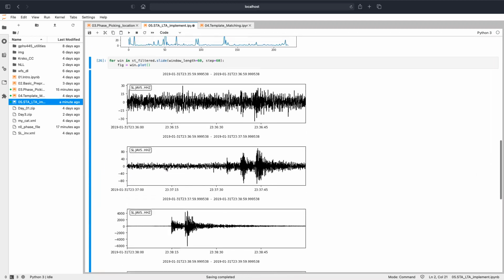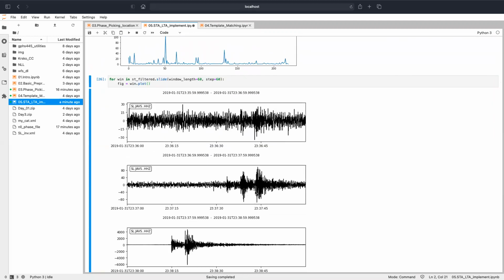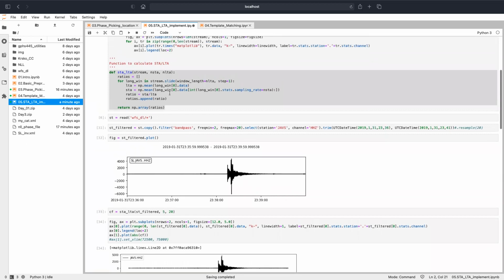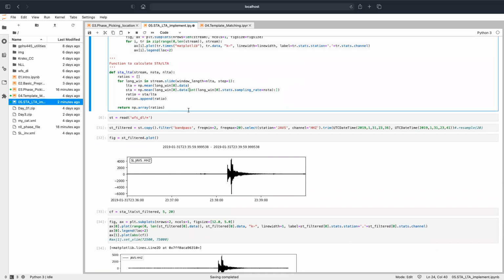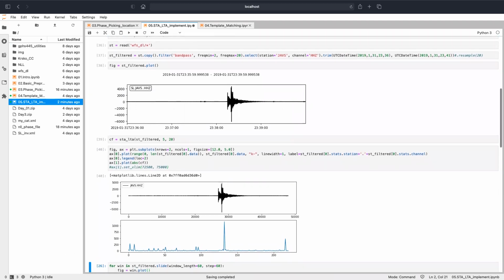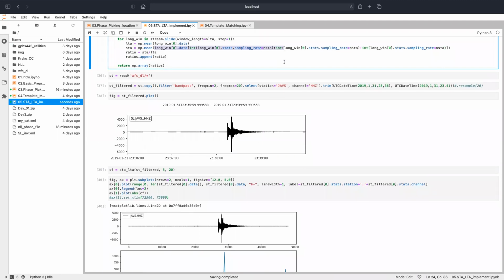This is the only answer I have for you now. I really did not go too much into detail here to understand this, but I think it's because of these 3 or 4 earthquakes that happened before, and because of the time window that we selected. I don't know exactly what happens here, but let's try to change this slightly to see what happens if I select a time window somewhere in between. Okay, I think this is fine. Much better. Yes, because as I said at the beginning, first I selected the first samples of the long time average, then I selected the last samples, and now I took some samples in between.